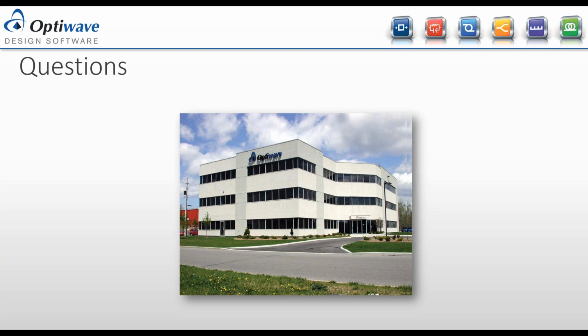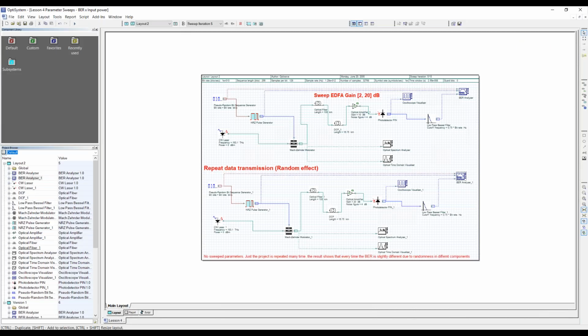Okay, thanks, Brian. Okay, so I have a couple of questions here. One about the nonlinear refractive index. As I mentioned in the setting of the fiber, the nonlinear refractive index, which is N2, you can either set using a single value. If you have a constant, let me show you here.